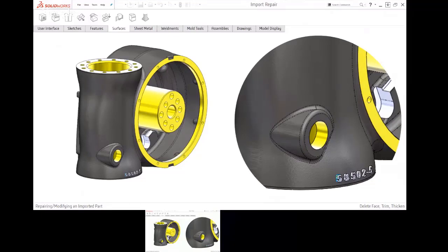You get free 2.5 axis milling in every license of SolidWorks. And it's tolerance-based machining. So if you put model-based definition or model-based dimensions on your part, the CAM software understands that, hey, this hole has this tolerance. We know how to do that. No need for a drawing. Less and less need for a drawing. So pretty interesting technology. Good question.